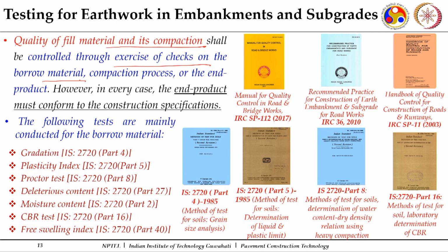As we mentioned in the earlier slides, there may not be a sufficient amount of cutting or soil available with you. So, you may have to select a nearby borrow area, and then evaluate and judge whether that soil is suitable, and if found suitable you can use it for your construction. You have to regularly monitor that the soil coming from the borrow area is meeting your requirements, as per the standard requirements which have been considered for the design